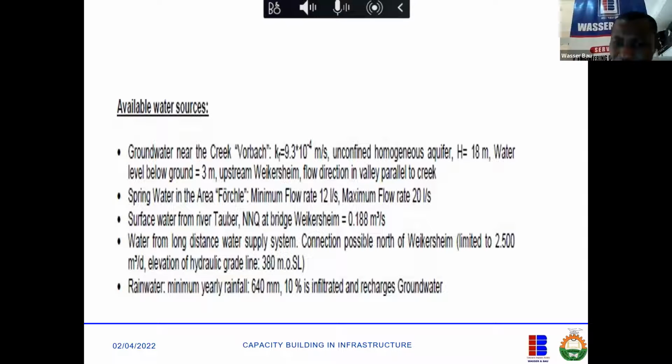That's the first step. And what does aeration do? What aeration does is basically to give it oxygen. If you remember our equation in school, if you feed iron 2 plus with oxygen, it becomes 3+. And 3+ is not soluble in water. It floats. But floating is not enough. You now put sodium hydroxide, calcium hydroxide, aluminum sulfate, and many other chemicals. Those chemicals will go and replace those ions and make them float. I'm not a chemist, I'm not good in chemistry, but that's what happens. The ion will now float.